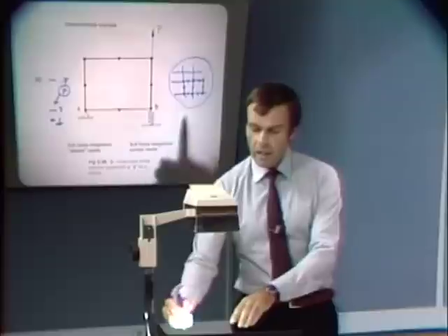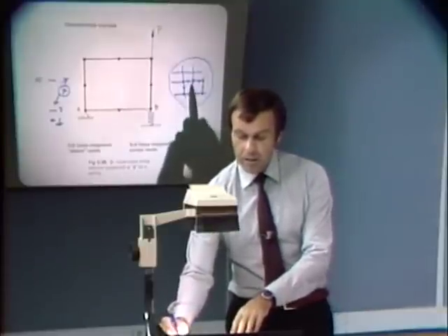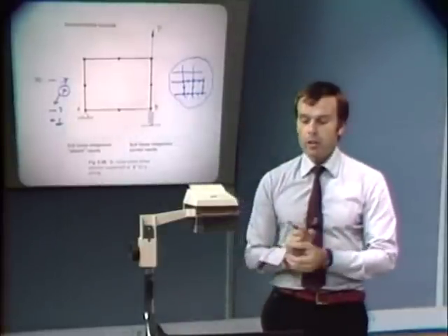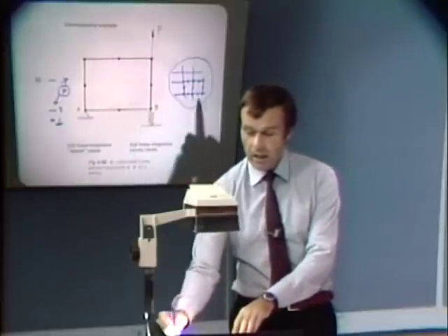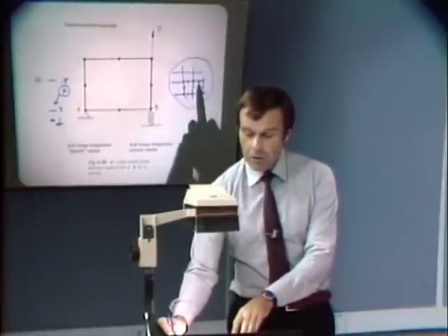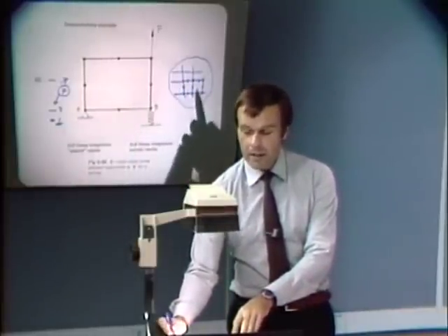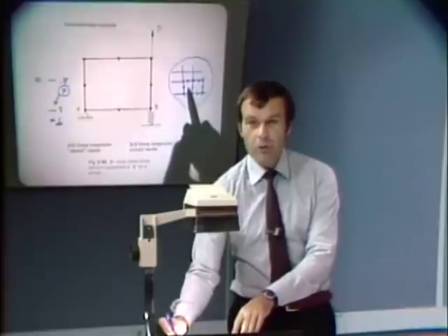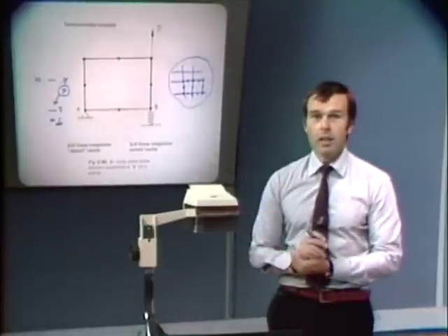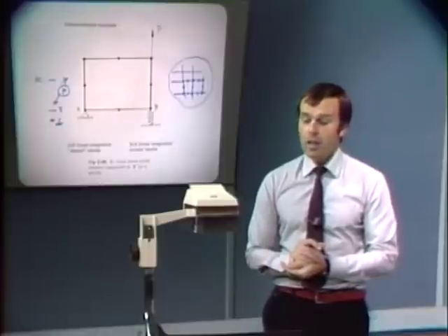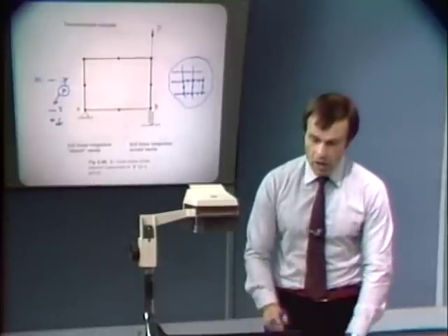In other words, although this one element is unstable when we look at it numerically, when we solve the equations for a single element, as shown here, when the element is surrounded by other elements, they provide enough stiffness into this element so that the overall solution of the mesh can still be obtained, and we obtain, in fact, good results.